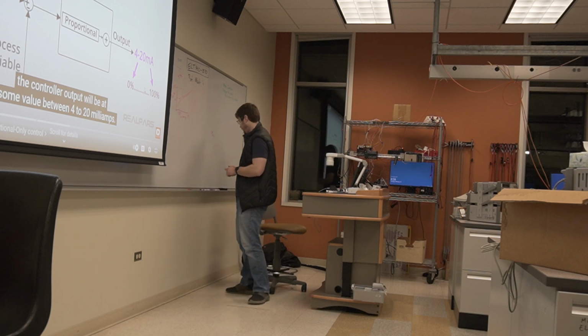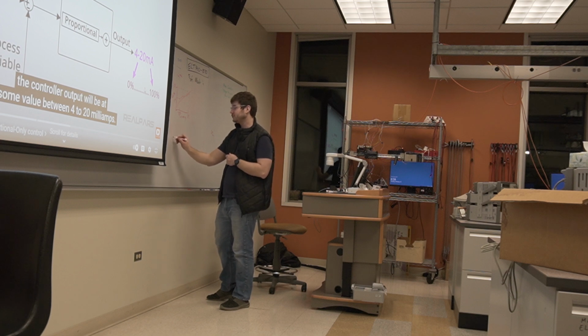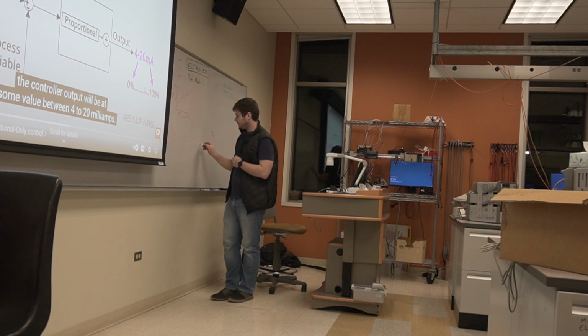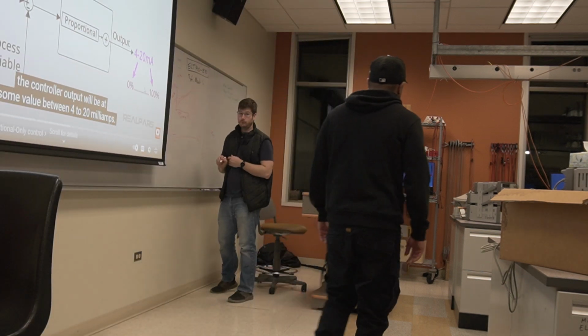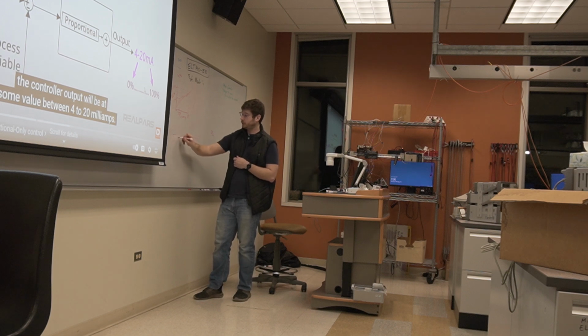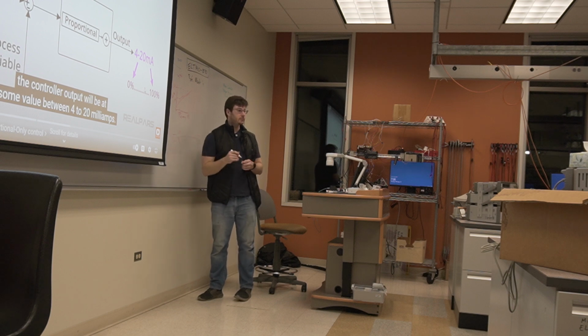Okay. However, over long distances, if I have my little sensor over here and I have voltage running on this line, and that guy's connected to my PLC all the way over here, voltage droops over this line, all right? If I took a multimeter and measured this signal, I might get 2.8 volts. If it's 25 degrees C in the room and I read 2.8 volts, I know that's 25 C, that's what I expect, right?